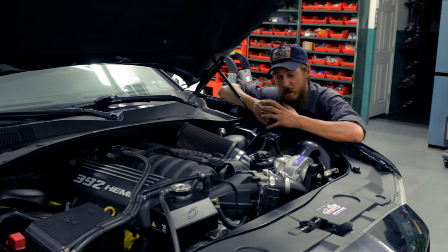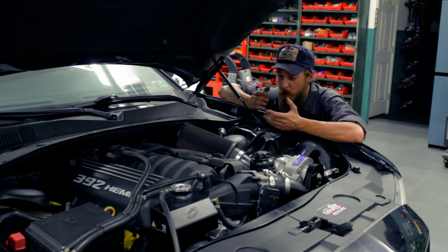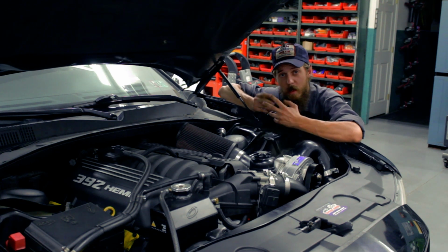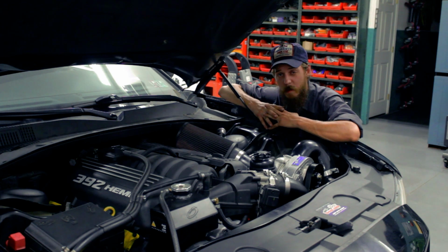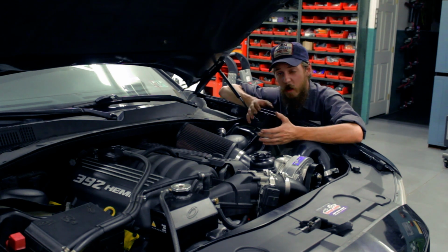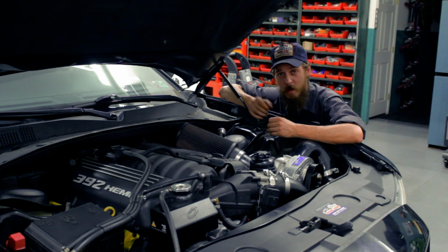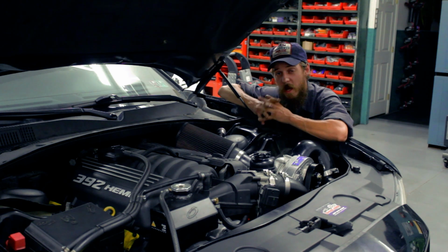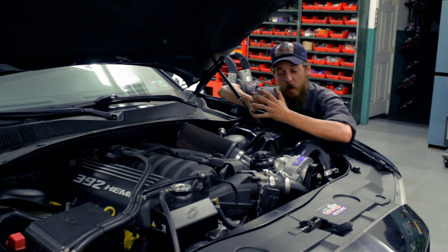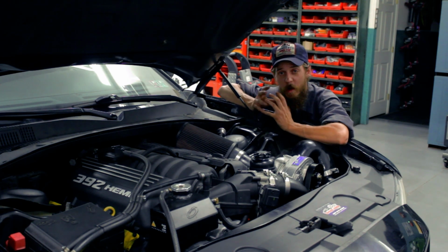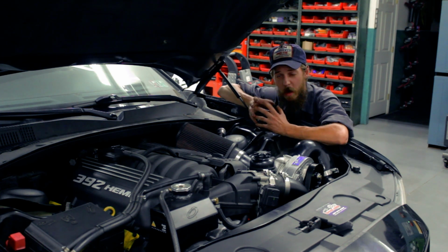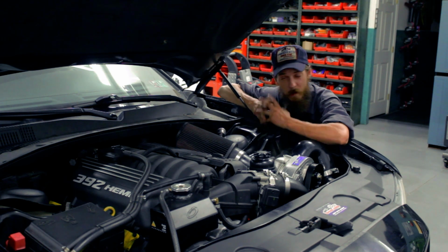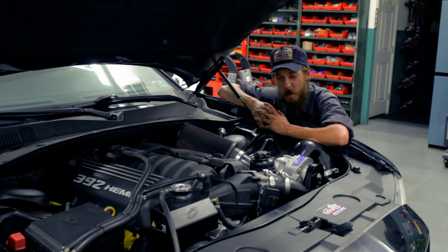And I'll say the last little bit was multimeter. We hooked into one wire and confirmed a scan data reading. We then used that same tap into the wire to run 12 volts to it to simulate a correct operation of the switch. And we had correct data PIDs in the scan tool at this point, and we had full correct operation of the starter circuit, the crank. So, kind of cool, kind of different. Something I haven't run into.